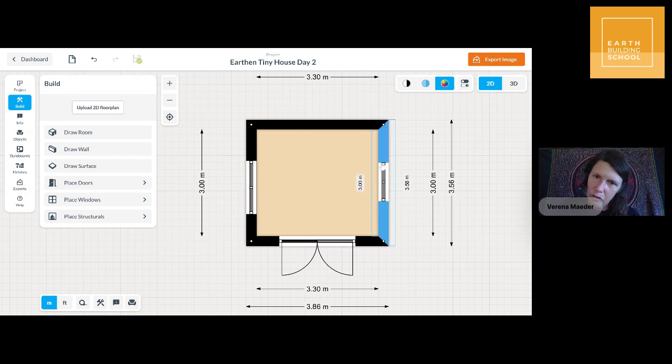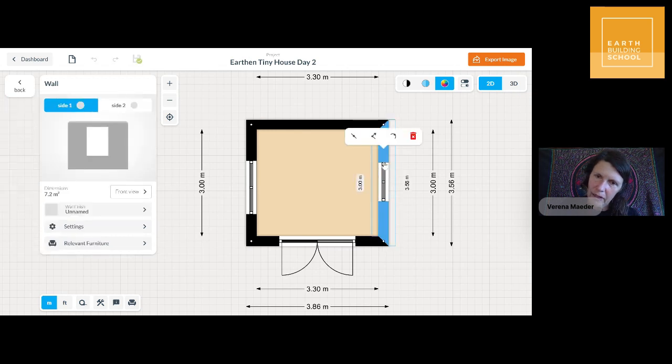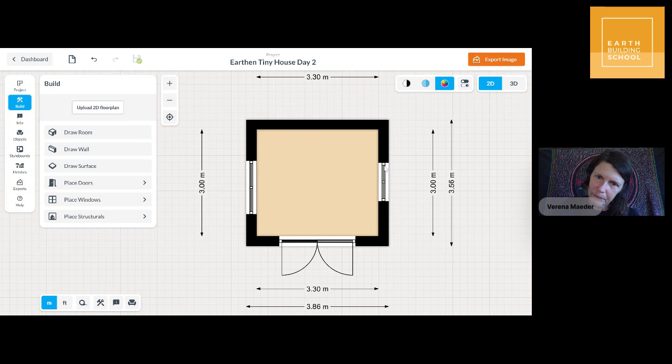And here, just to show you what I meant with the size, if you look at that measurement on the outside there, which at the moment says 1.11, that's not within brick module. So the brick module is a multiple of 0.15. So more than 900 would be a 1.05 or a 1.2. So I'm going to go to a 1.2.